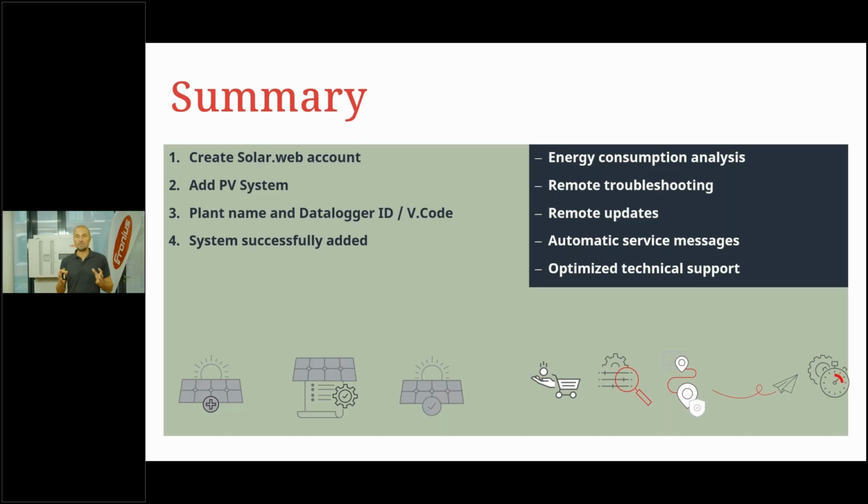Good. This was the information from Solar.web. As a summary, just to repeat once again: create your Solar.web account first with your email address. Add your PV system with the data logger or serial number of the inverter, and then you have it included. Main advantages, again: you can do a consumption analysis.